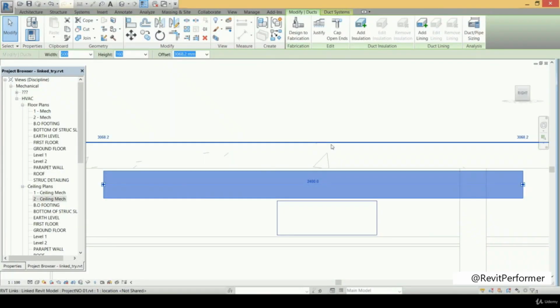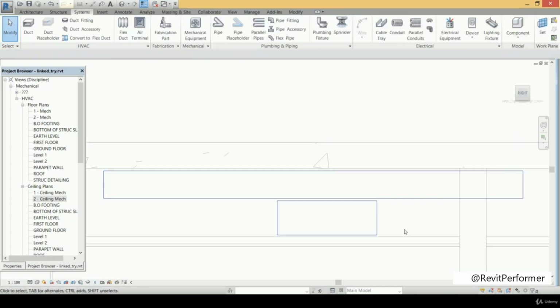Also, the second note to take into account is that the pressure losses and the air losses inside our duct after making those modifications must be in the acceptable range. And finally, the cross-sectional area of the new resized duct shouldn't be less than the cross-sectional area of the old duct, as we said before. So if we achieve those conditions, we can resize our duct to provide additional length in the vertical direction. Very good. So that's about our first solution.